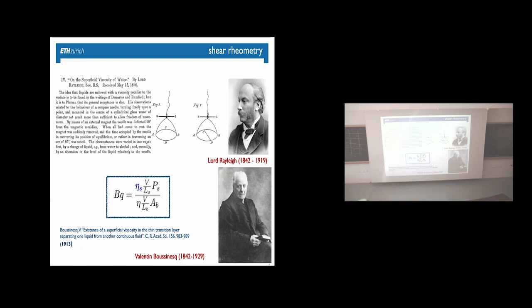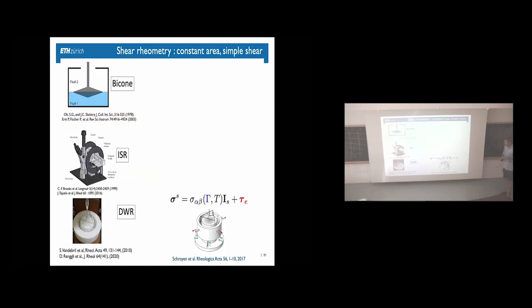So I have the surface viscosity for a viscous film, the velocity of the probe that decays over a certain length scale, the velocity gradient, acting on the parameter of my measurement object. And then I have on the bulk side the bulk viscosity, the velocity, which is probably the same, the length scale, which is probably the same, and the area. So the ratio of parameter per area will determine which ratio of viscosity you can measure, surface viscosity. And this has been a guidance for different experiments. And so different experiments have been made.